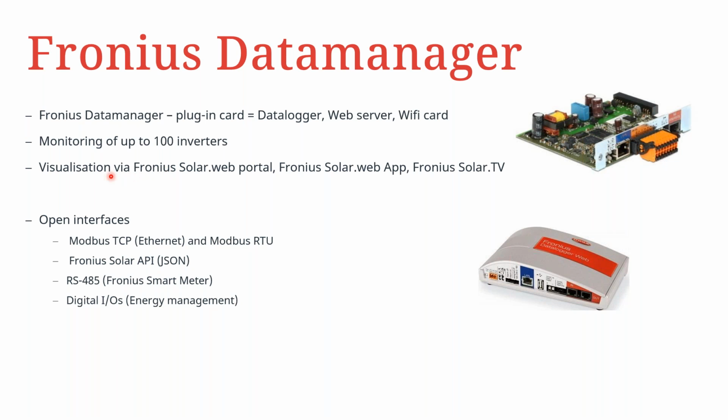With the help of the data manager, we can of course visualize data via the Fronius SolarWeb portal, the Fronius SolarWeb app, and then of course via Fronius Solar TV. To be able to do this, it makes use of our open interfaces, which include Modbus TCP, popularly known as the Ethernet port, and Modbus RTU, which is basically a point-to-point wire protocol.